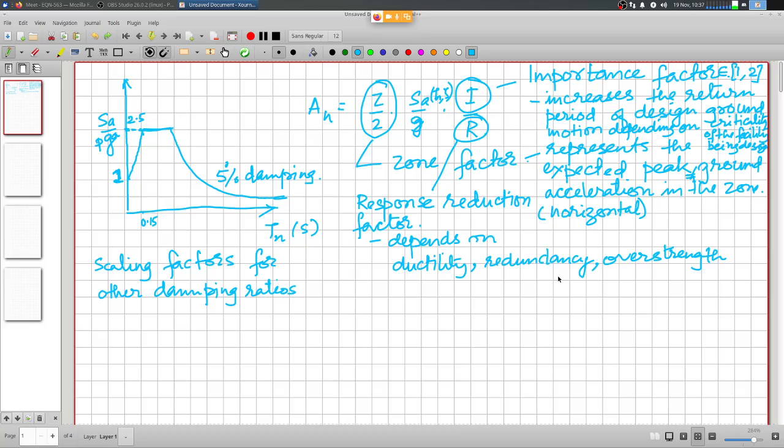Another important source of overstrength, and I would say it is of course contributing to overstrength, but it is actually detrimental to earthquake resistant design, is this: the material, the reinforcing bar, for which it is qualified, the yield stress or the rating for which it is passed as a particular yield level, guaranteed yield, the actual yield strength of that bar might be much higher.